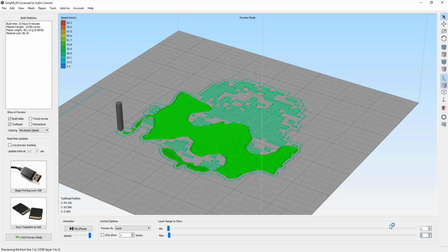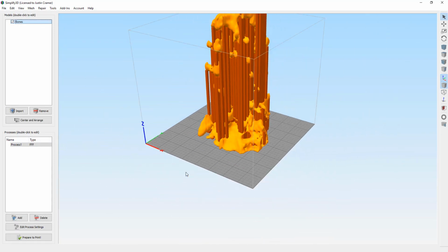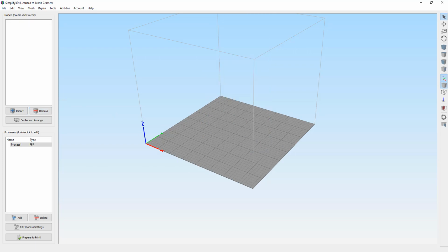And then if I go up to layer 2, I see it's printing a full base. So it's printing this over midair, and of course it didn't adhere to the build plate because it wasn't being instructed to. So when I went back and looked at the model, I discovered that it actually wasn't perfectly flat along the surface from my segmentation. So what I did was I went in and did a plane cut and made the model perfectly flat. So if we remove that, I'll bring in my trimmed model.